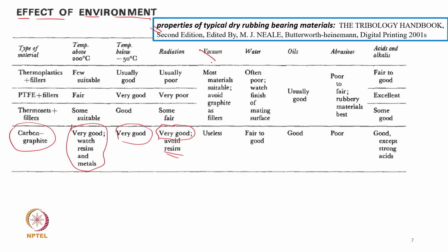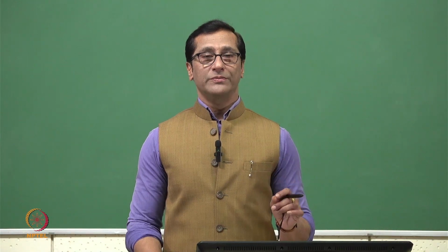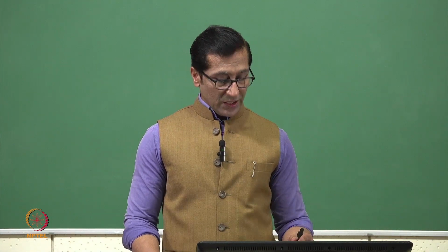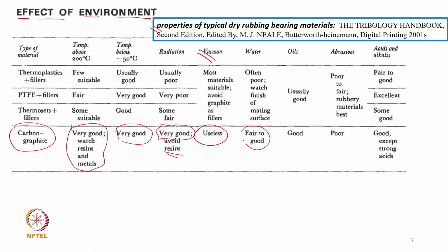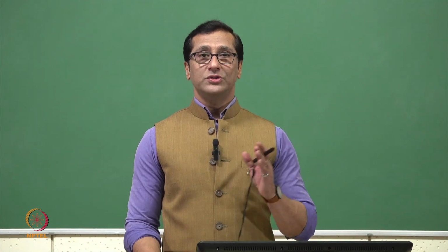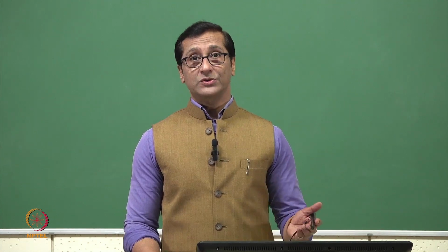Now, particularly in the vacuum case, it becomes useless. We should never ever use carbon graphite when there is a vacuum or low pressure case. And it gives a good result in water. Of course, I will show you one case study. If you use excessive water, then again it is bad. So there should be water, and there should not be excessive water.